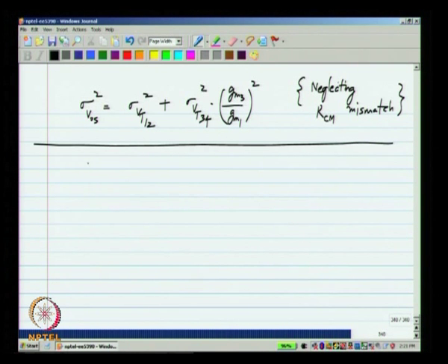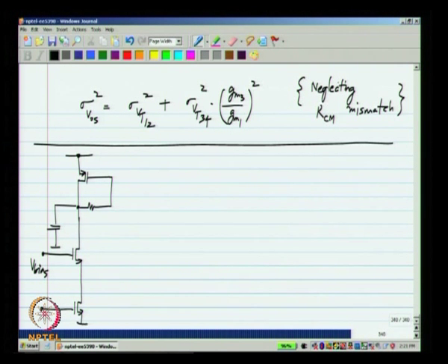And the common mode half circuit of this, which we also discussed earlier, there will be a parasitic here. Now, in this loop the integrator is formed by the Gm of M3 and 4 and this capacitor 2C.